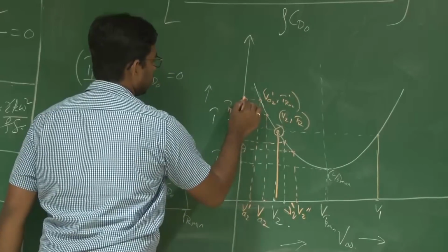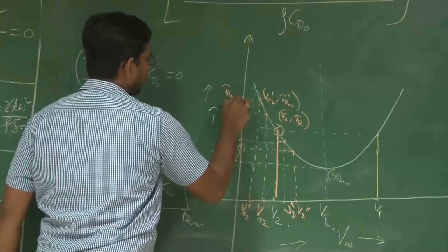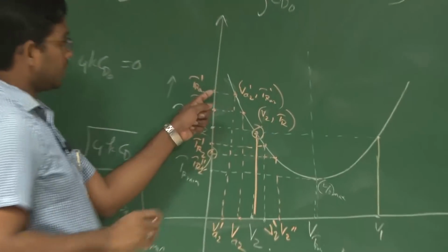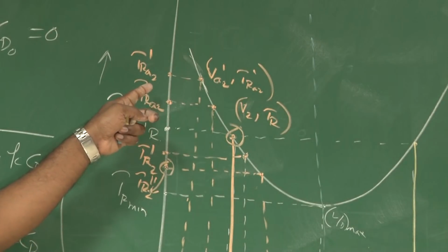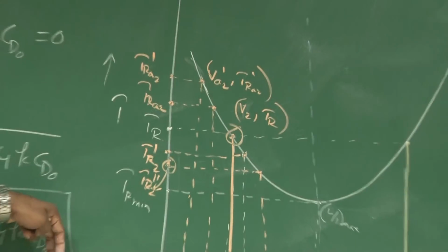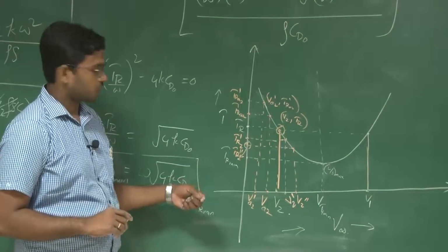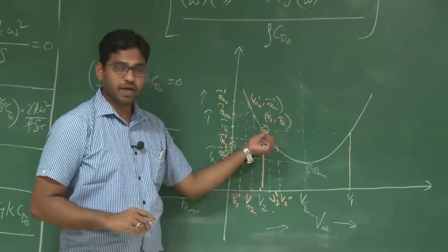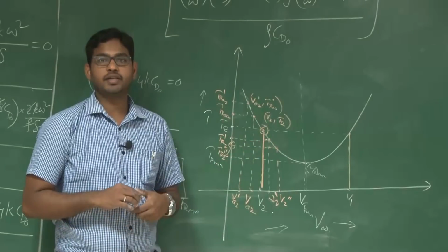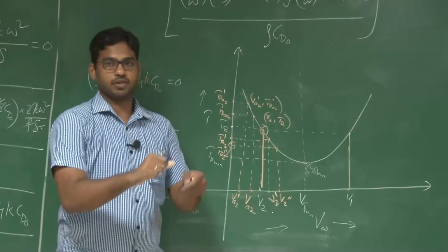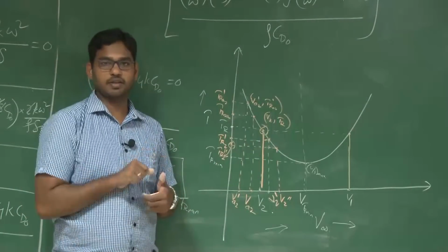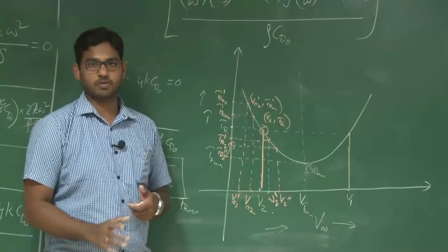So the thrust requirement has increased further, right, which will decelerate the system further. That means the UAV is not coming back to its equilibrium by itself. Either the pilot has to give a constant increase and decrease in the throttle, even for a small disturbance.